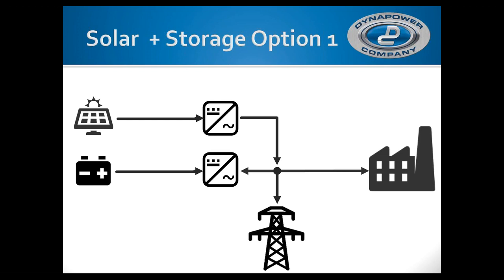Another consideration, of course, is that once you've done that successfully and you've created an island, now you've got to balance the battery with the load with the PV. There's some intelligence that's got to be built into this new inverter that's placed on the site, in this case the battery inverter, that is able to help manage that. Thank goodness there are a lot of companies out there that have gotten into this space, what I'll call the microgrid controller space, that can help do that balancing.